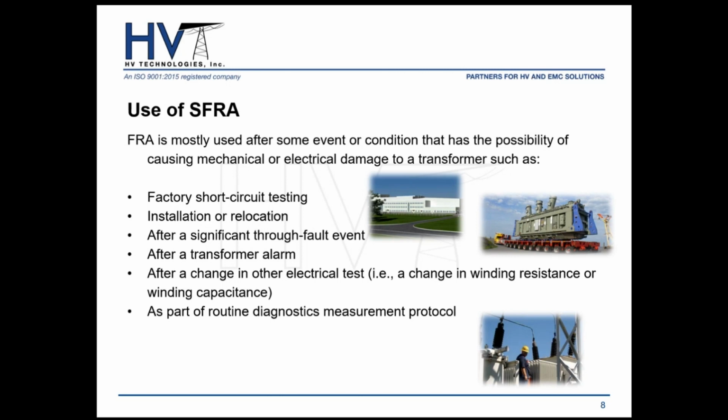Or maybe the transformer is equipped with different monitoring devices, temperature sensors, or relay, any sort of relay that can produce an alarm. If you have an alarm condition on your transformer, it's maybe a good idea to run a frequency response analysis just to make sure that everything is okay.